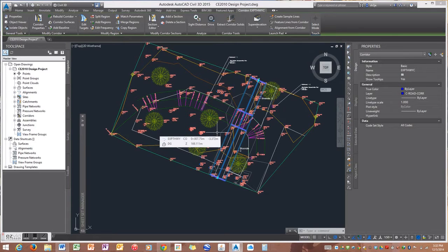The next goal that I approached was the ADA compliant pathway. There is a hill from the upper left of the design area down to the bottom right, and to cut in an ADA compliant ramp to get from top to bottom, I basically went through some trial and error to find the path of least resistance, which I determined was here, and this kind of contours down adjacent to the existing staircase.